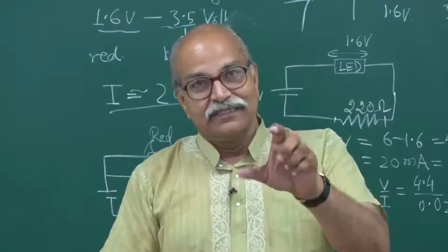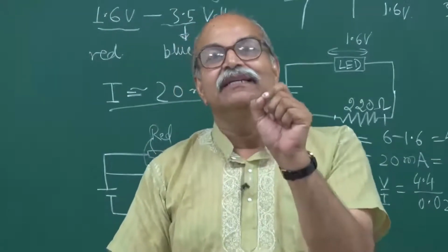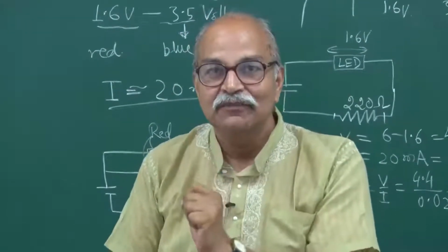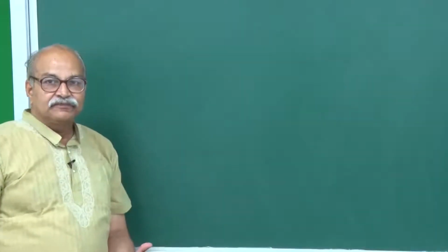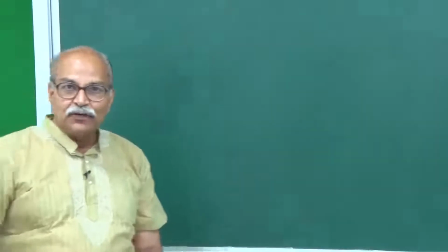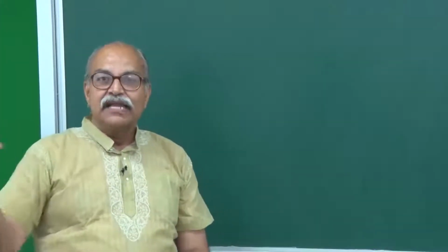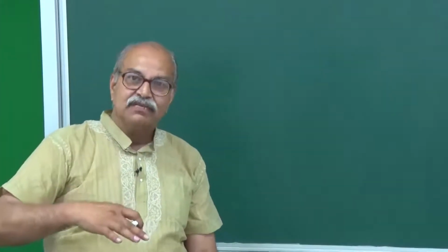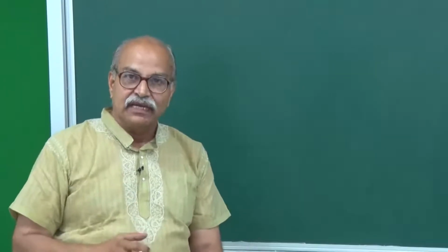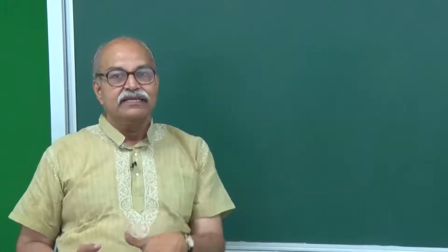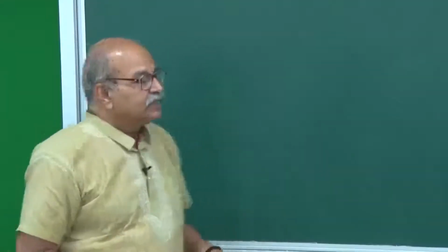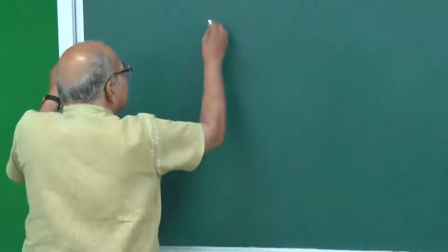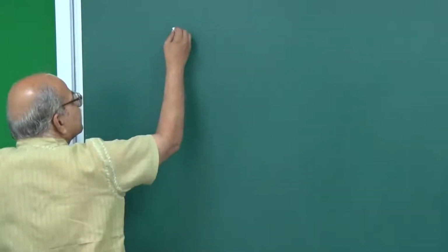So, what is it? The basic unit is again a PN junction, a silicon PN junction. In a solar cell, like photodiodes we talked about, light falls on this PN junction, and that light creates electron hole pairs. So essentially the same mechanism, but the construction is slightly different.